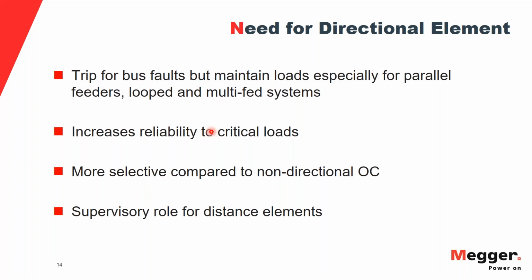And the other thing is, it also acts in a supervisory role for distance elements. Now, we all know that distance elements work on the principle of impedance calculation. So they have forward zones, they have reverse zones. So basically, the distance relay calculates the impedance, sees if the fault is in the forward zone or in the reverse zone, and it works on that principle.